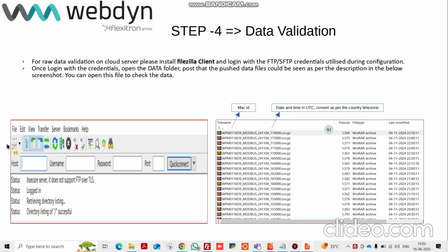Now, let's assume that your communication is healthy, your cables are good, your inverters, meters and sensors are communicating well, and their device IDs and Modbus parameters are done perfectly fine. Now we can move on to step 2, which is the configuration.